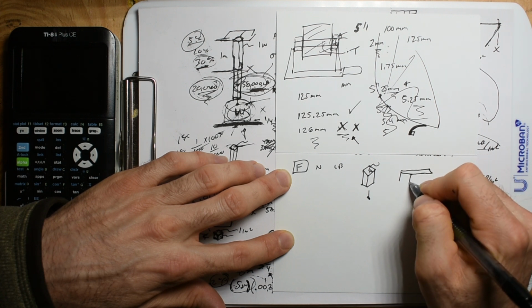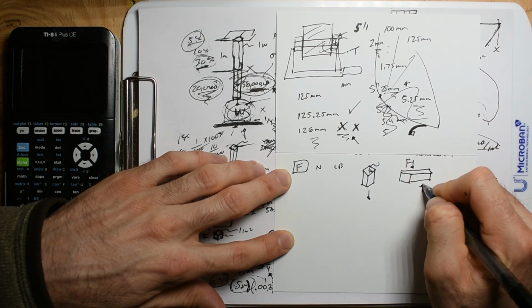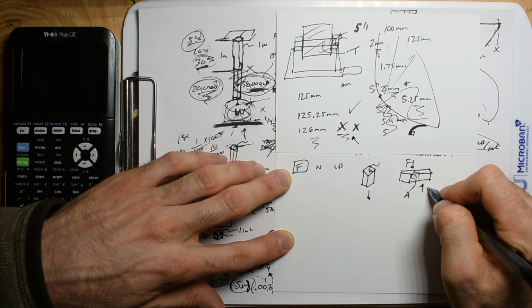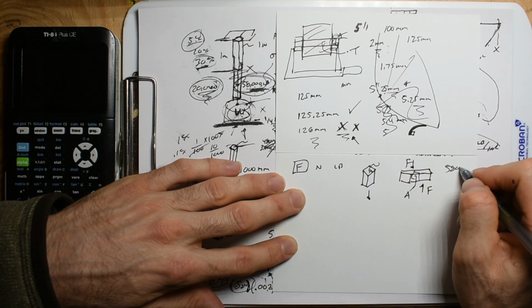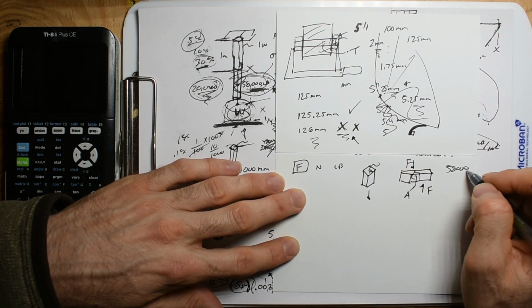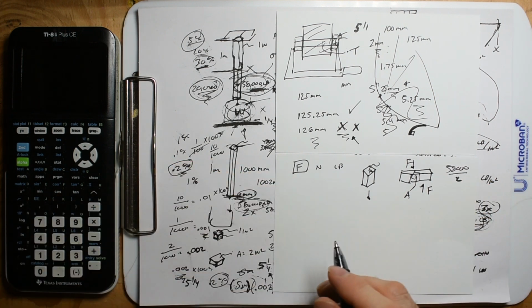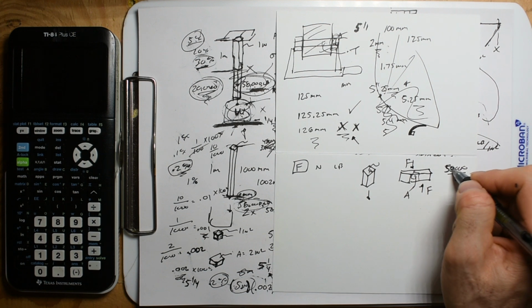You know what I mean? Then a conversion factor of a half. Like, hey, if this is the surface area that I'm shearing through, the strength isn't 58,000, it's 58,000 pounds per square inch divided by 2. You know what I mean? And that starts the process of using theory.